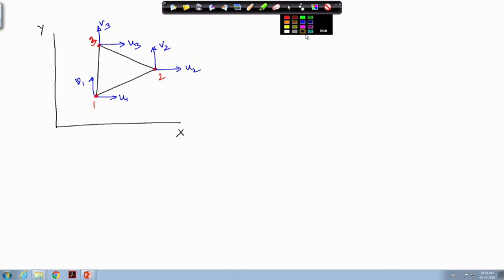So, in the case of truss, we assume that your u is equal to ax plus b, a linear function. Then in the case of beam, we assume it is a cubic function. Similarly, here also you have to start with an assumption. Now, what form you take, whether it is linear, quadratic, cubic, that depends on what information you have and whether that information is sufficient to find out the constants associated with that approximation.